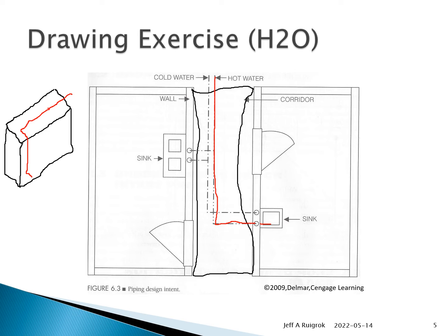Then we'll do the double sink on this side. I'm using an interference style of drawing here. I'm breaking the line, or highlighting the upper line and hiding the pipe in the back. So foreground, background. And that would go out of the wall the other direction.